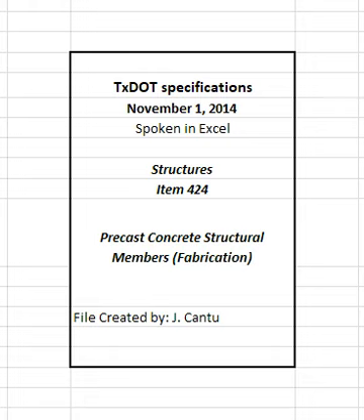4.2.7 Curing of concrete. Cure concrete to promote early cement hydration by providing adequate moisture on exposed surfaces and by maintaining the concrete temperature or curing enclosure air temperature at the concrete surface within the limits specified in this section. Provide uniform temperature and moisture on the surfaces to prevent differential shrinkage that may cause warping or cracking. Prevent temperature differentials within the concrete that cause thermal cracking.